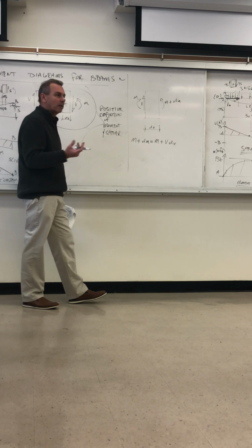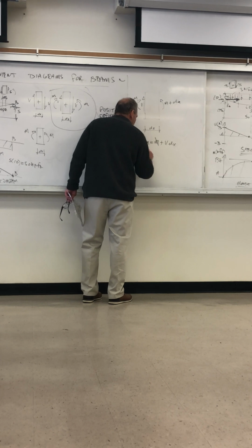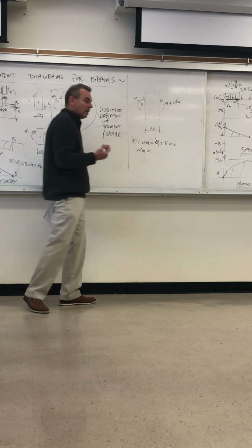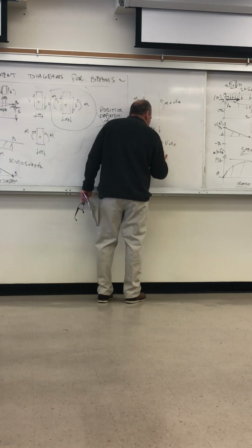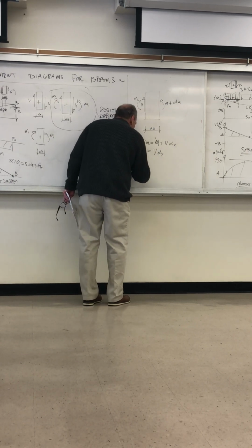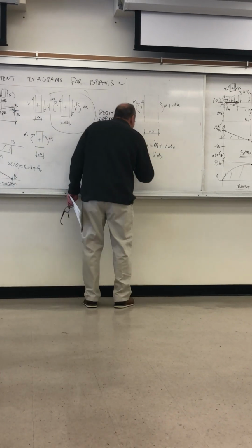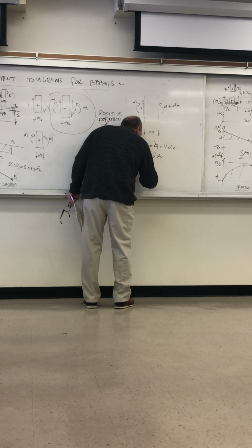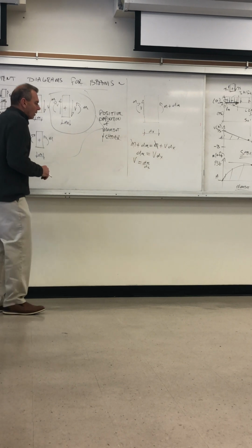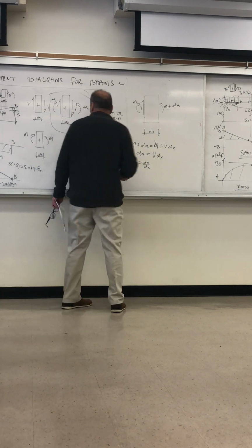There's the same moment on the left and the right of the equal sign, so that cancels. And we have dM, the differential moment, is the shear, not a differential shear force, the actual shear force, V dx. So what's interesting is we can see that V is the ratio of those two differential terms, V is dM/dx. dM/dx is just the slope of the moment diagram.